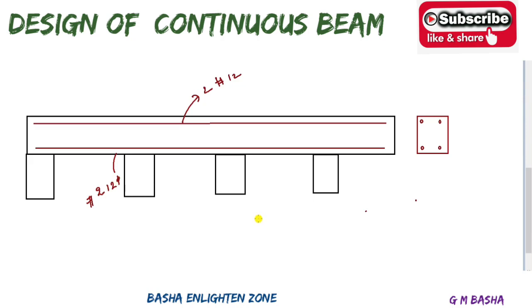But according to our condition, what is the mid-span range? For mid-span, it requires minimum 3 bars, and 4 bars of 12 mm diameter at the supports. Where will you get the supports? Supports will be at this position, here, here like this. So these are the supports. And what are the middle spans? Here, here. So for the middle span, minimum 3 bars will be required. For supports, 4 bars will be required. Means